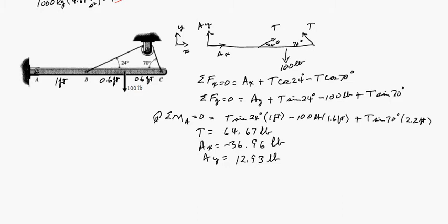For our pulley, we're going to work in the standard XY coordinate system. Here's the free body. Sum the forces in the x, sum the forces in the y, and sum the moments about point A, choosing point A to simplify your algebra, and solve the algebra.